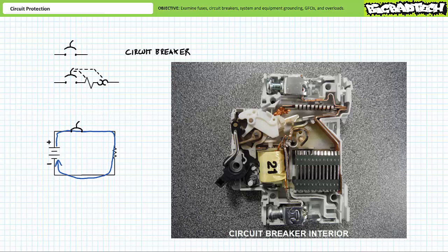This rapid and forceful opening is a means of extinguishing the electrical arc between the moving contacts as they're pulled apart. Additional precautions are often used to minimize this arc. Larger circuit breakers use arc chutes to cool and divide the arc. Blowout coils or other magnetic means deflect the arc into the arc chute. Gases with a strong dielectric strength, a property we'll discuss later, like sulfur hexafluoride, SF6, quench the arc in gas circuit breakers.